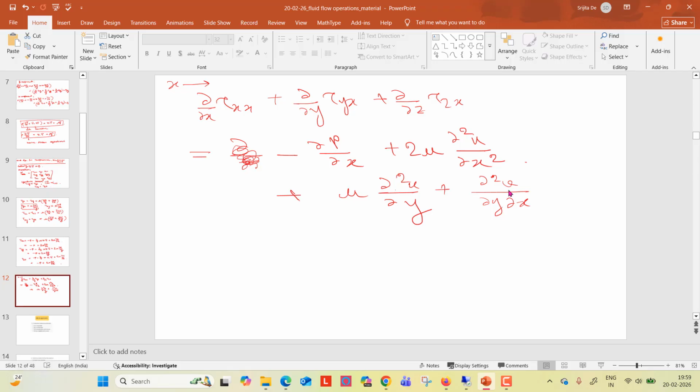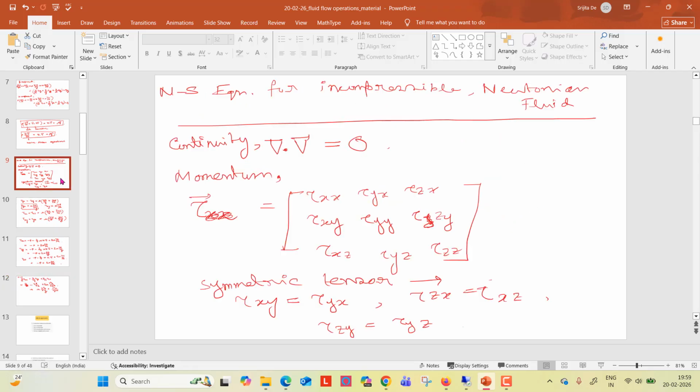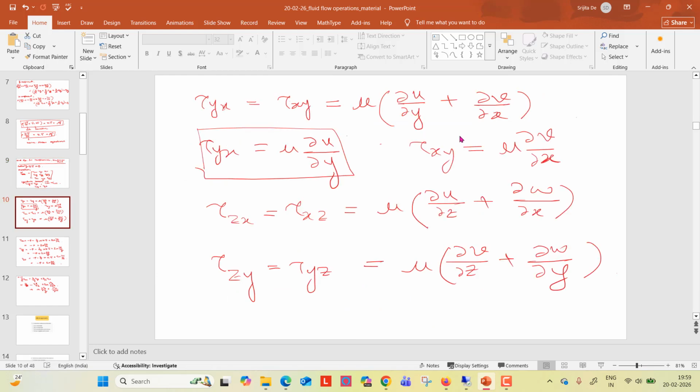And for the last term, del del z of tau zx, it will be mu del 2u del z2 and del del z of del w del x.